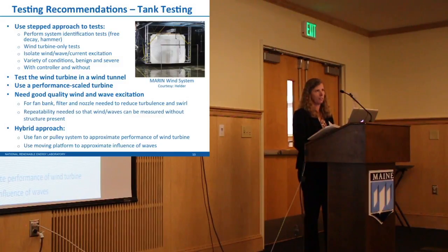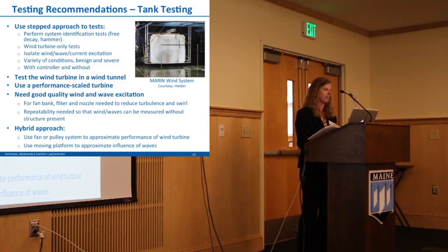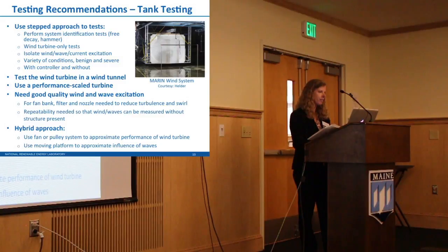Ideally, it would be great, if you are going to a tank test, to be able to test the turbine actually in a wind tunnel before you put it in the tank. The wind quality in a tank is not that good, and you're never going to get really the great measurements that you get in a wind tunnel. So if you really can understand the turbine before you go into a coupled sense within the wave tank, that would be beneficial.